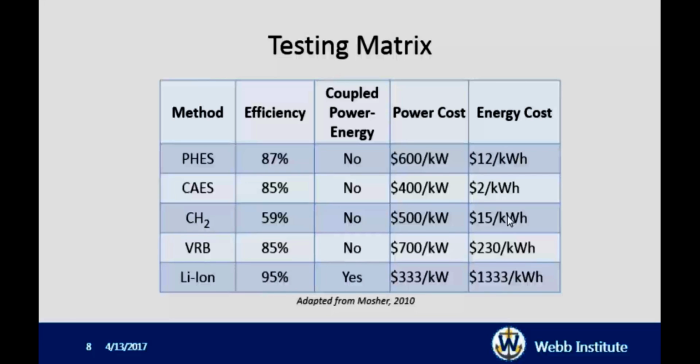So in that case, it's useful, and what I've determined through a key aspect of this, it's most useful to have your energy storage system for large-scale applications like this one, to have decoupled power and energy characteristics. So you can simply increase the amount of energy you need with a constant amount of power for a certain area, certain demand in an area. Additionally, I've put on the power and energy costs. Since most of these are decoupled, or in the case of lithium-ion, they're related, the power and energy cost of each kilowatt or kilowatt hour of each system is included.